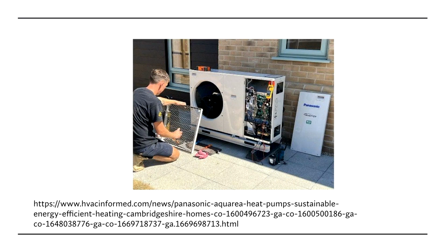But you see, he's basically pulled the grill off the fan to get access to the indoor coil. And he could, if he wanted to, where he's got some of his tools laying on the top, easily pull that top off and then be able to spray down in there. The interesting thing is once you get this grill off the front of the fan, you can easily get access to the inside of the coil and use a hand pump pressure bottle and basically blow that stuff away.